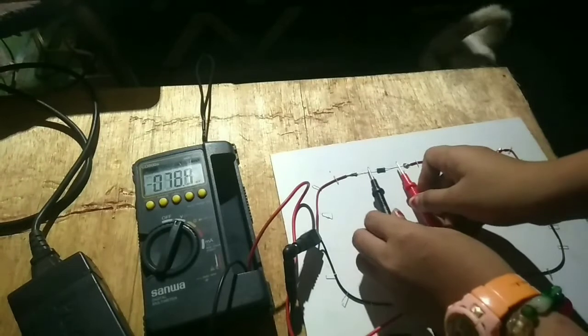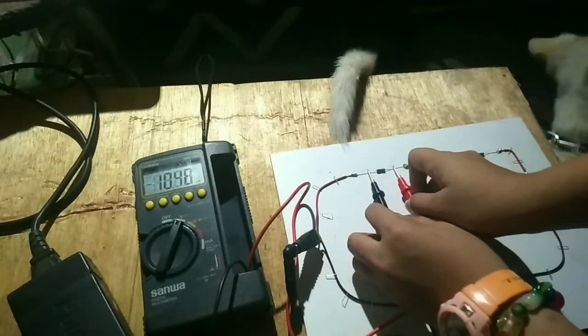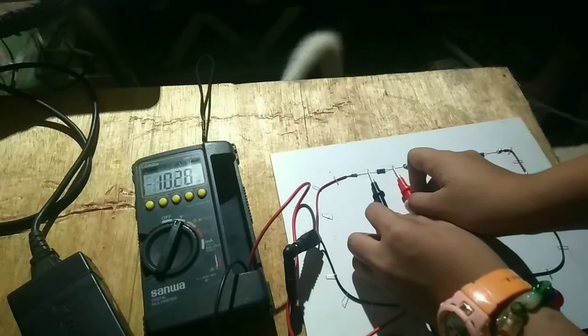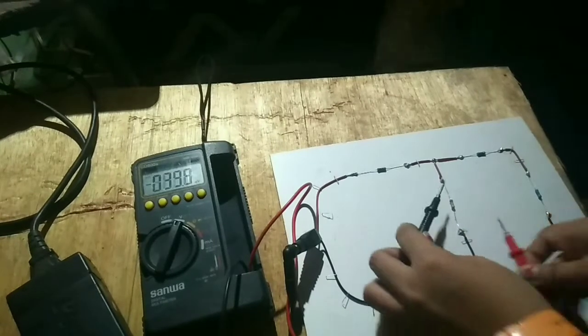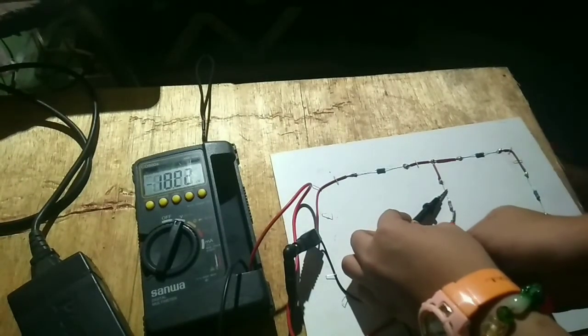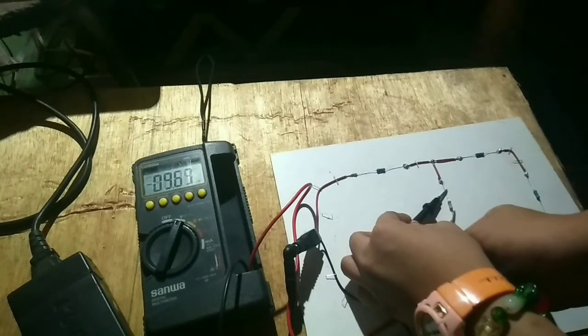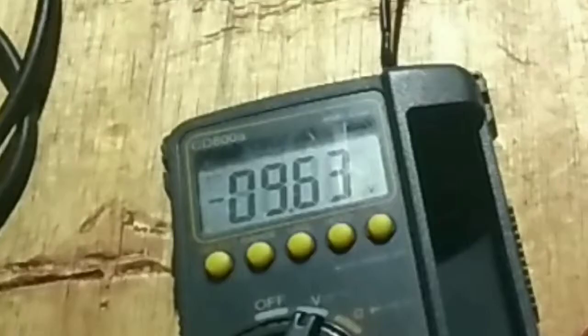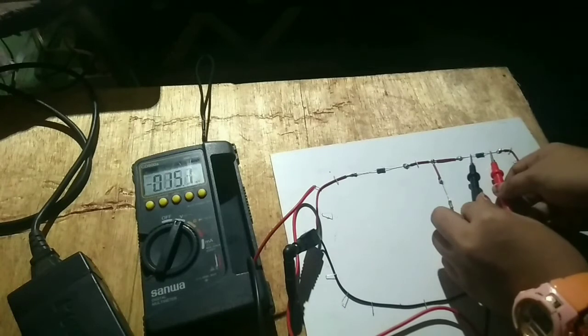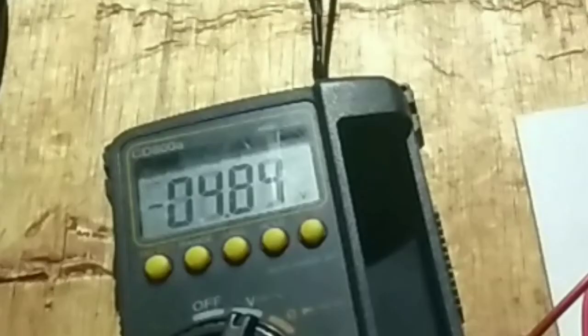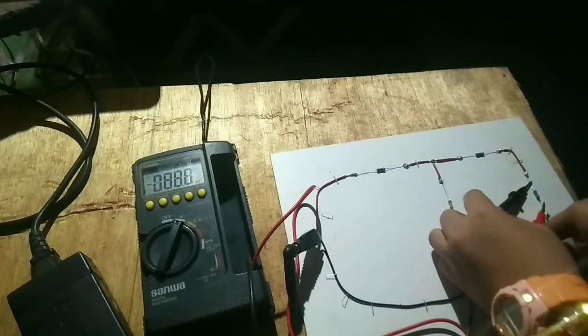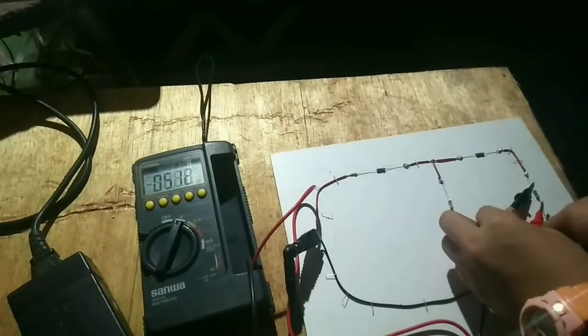At this point, we will measure the voltage across resistor 1. The multimeter is connected on each side of the resistor in order to detect the voltage that passes through the resistor. The same goes for the other resistor, where we place the resistor in between the test probes to measure its voltage. We did the negative to positive measurement in order to get a negative value of the voltage. So when we get the summation of all the voltages in one loop, we will get 0.